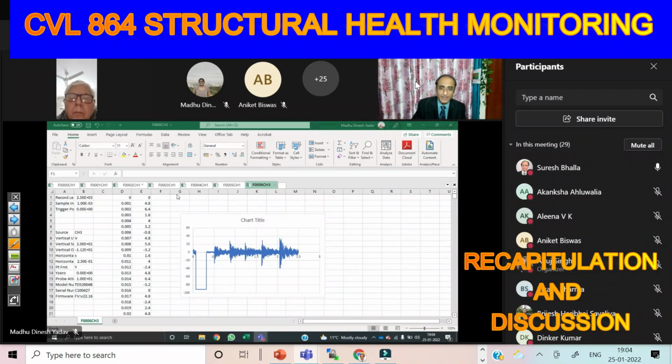And the values for the ESG and the vibrating wire strain gauge, the frequencies, everyone must have noted at that time, so use those values. The last digit might fluctuate, after the third decimal place, because the beam was under bending, so there may be fluctuation, but use your own value. We are not checking what value you are producing, but we are just checking that you are able to convert that into physical values of strain.